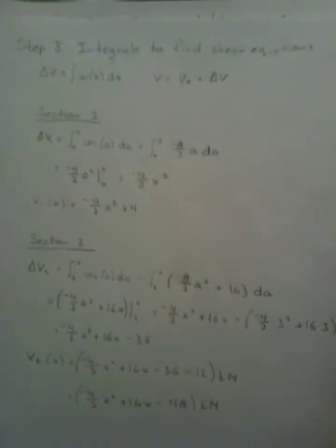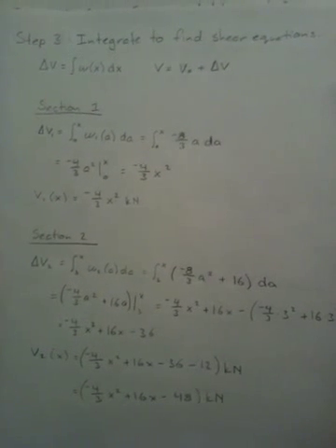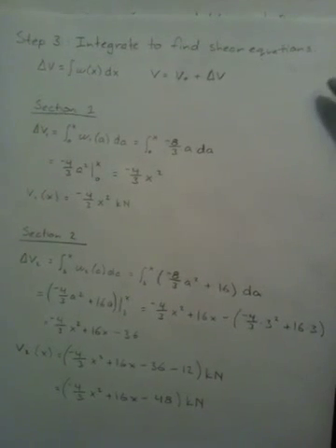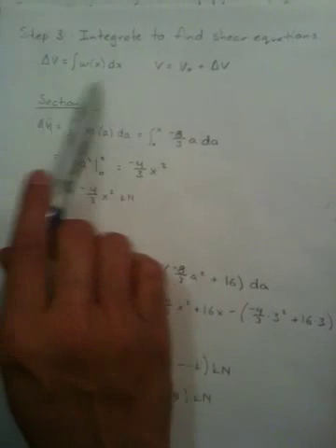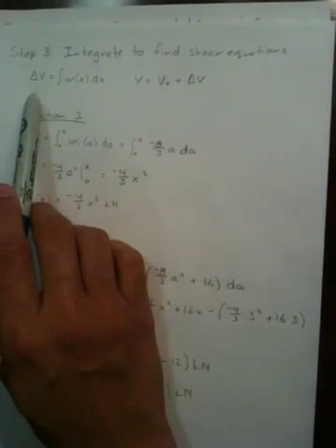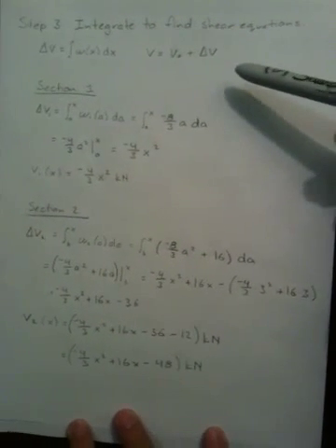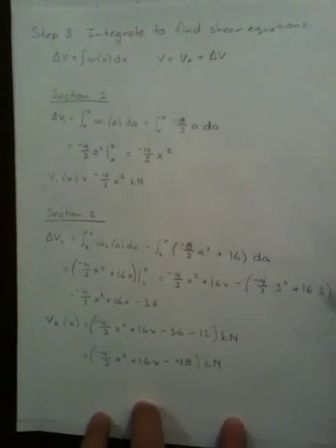Moving on to step 3. Here we'll be integrating the equations for the distributed load to get the shear equation. Keep in mind that this integration only yields the equation for the change in shear. We will eventually have to account for any point loads, but we'll get to that later.